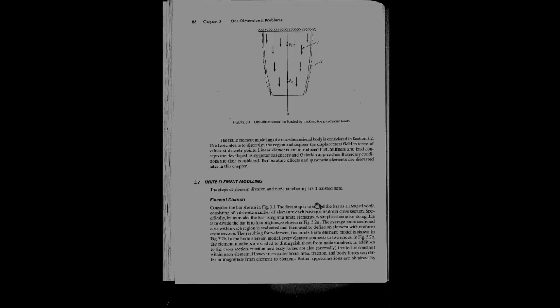In the finite element method, we typically divide the structure into multiple elements. So far we've only looked at dividing the structure into one element only. Specifically, our elements were slightly different to these. Look at these. These elements only have 2 nodes per element. So there's element number 1, with only 2 nodes. Ours had 3 nodes. So we looked at the quadratic element, the one that's in 3.9.